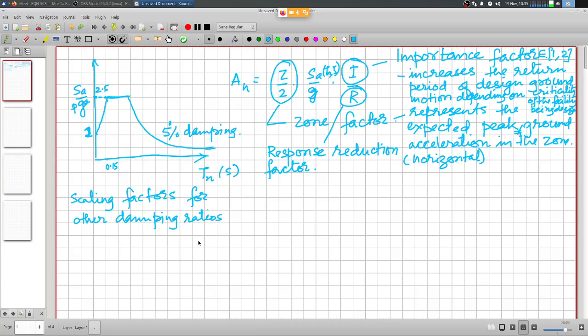So it is extremely difficult to verify the results of nonlinear analysis, and hence it is preferred to stick to linear analysis for the design of facilities, and therefore we bring down these earthquake effects by a factor of R, which depends on available ductility,